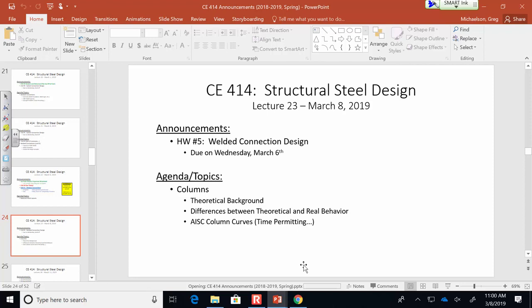starting today, but really the way that we handle things in steel design, they kind of change a bit. We're going to be relying a little bit more heavily on some design aids in the manual. A lot of our theory and ideas are going to start to change because the overall theme of what we do in steel design changes when we start talking about things in compression. Things in compression like to buckle. And how we handle buckling and the concept of stability is way different from tension members and connections, because even with tension members and connections, you don't have to worry about that instability.